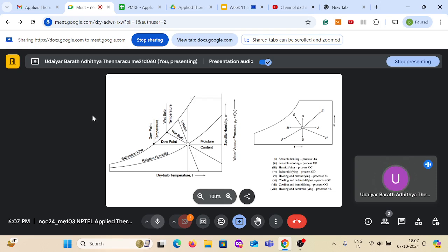So this is how a psychrometric chart will look. Again, this comes for different conditions. Generally what is available is for ambient pressure, and this may not be used for different altitudes and pressures, so you use appropriate charts or corrections for that.